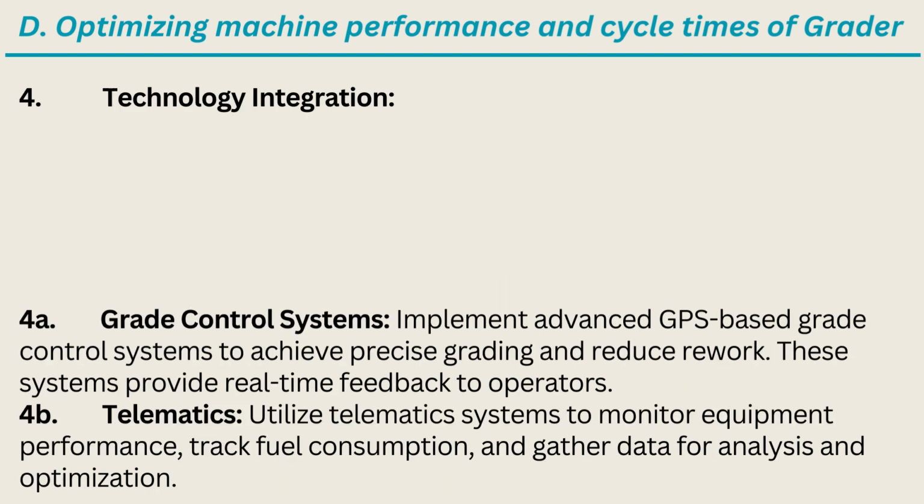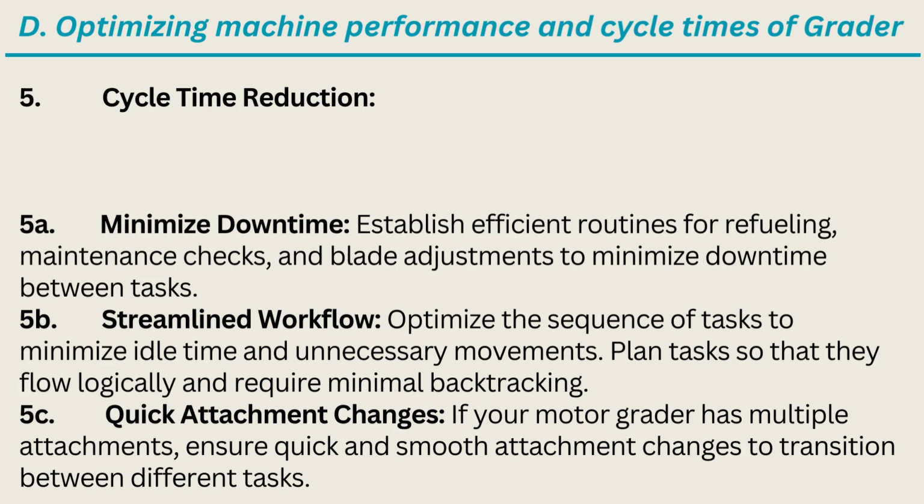4. Technology integration. 4A. Grade control systems. Implement advanced GPS-based grade control systems to achieve precise grading and reduce rework. These systems provide real-time feedback to operators. 4B. Telematics. Utilize telematics systems to monitor equipment performance, track fuel consumption, and gather data for analysis and optimization.